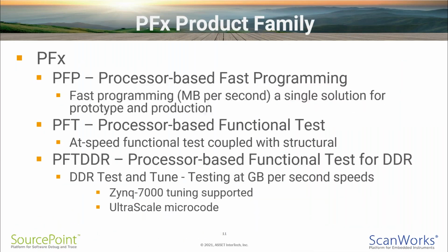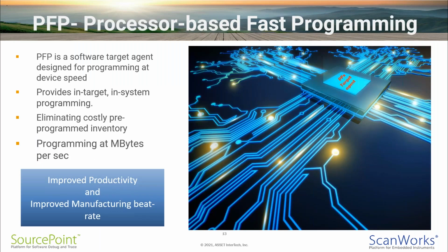PFX is a trio of tools within the ScanWorks platform that target specific engineering tasks to save development time, optimize memory performance, and promote better test coverage. These tools provide target resident agents to shorten the time frame between prototype and production when using ARM-based SoCs from Xilinx or NXP. Today, we're going to focus on the processor-based fast programming, or PFP. The processor-based fast programming is the tool that uses the processor within the SoC to program a suite of flash devices at near device speeds without a bootloader, an OS, or application present within the UUT.